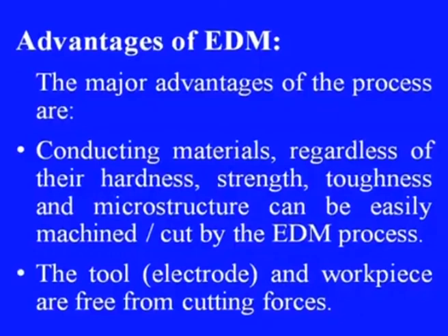Now, let us have a look at the advantages of this electric discharge machining process. The major advantages are: it is useful for conducting materials regardless of their hardness, strength, toughness and microstructure. This is what I have indicated at the very beginning.